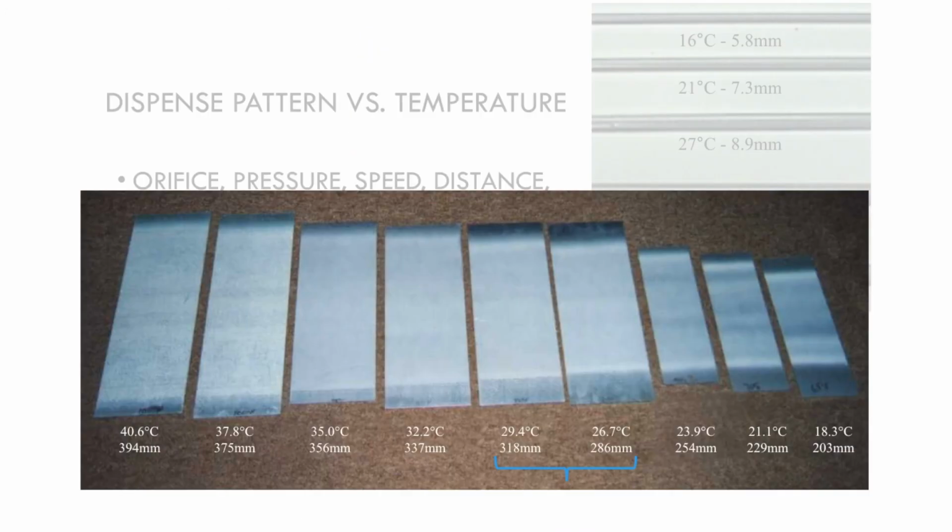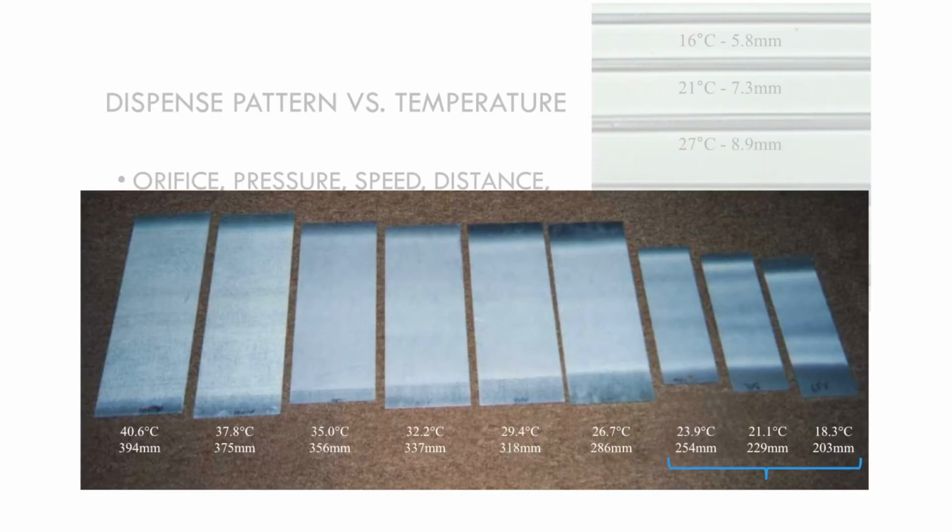Below 30 degrees, we see heavy edges beginning to appear, which are often associated with striping on the finished part. As we move into the 25 degrees C range and below, we see the combination of very uneven coating surrounded by heavy edges. This makes it very difficult to get a smooth, even coating on the finished part. Without a smooth, even coating, both performance and appearance will be compromised.